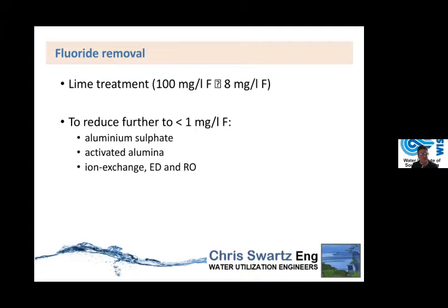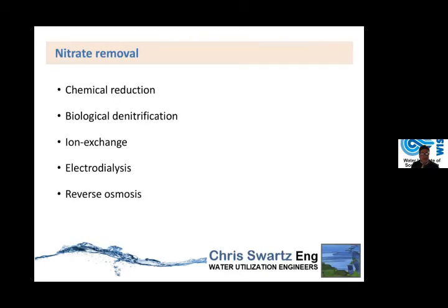But there are still some countries that do fluoride addition to the drinking water. Some of the technologies to remove fluoride are activated alumina or dosing with aluminium sulfate. You can use membranes, reverse osmosis, electrodialysis, and also ion exchange. For nitrate removal, I mentioned briefly chemical removal. You can do it biologically, and then again your membranes and ion exchange.